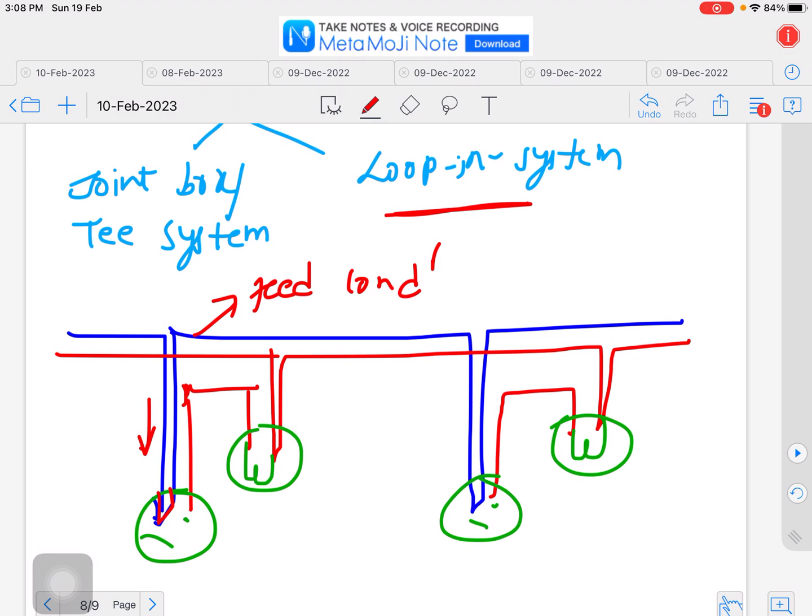The switch and the light are carried around the circuit in a series of loops. It goes from input to the next stage until the last point is reached. Actually, this looping is generally done inside the switchboard or in the box. Even the neutrals are looped in, either in the switchboard or from the light or fan.